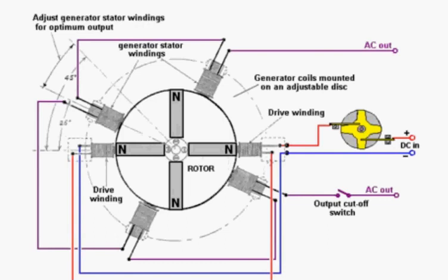And the cunning part is that the power to the drive coil is then cut off. When it's cut off, you get a back EMF pulse in the coil, and that reverses the magnetism of the coil, and that pushes the rotor on its way instead of hindering it.